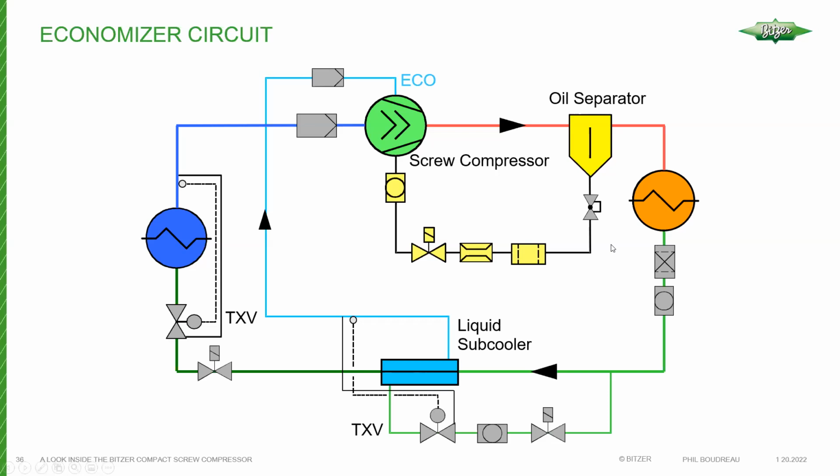So if it's a system that's designed for 105 condensing, if we factor in a little bit of subcooling, maybe you're running 100 condensing, something like that, 95 condensing. But when we enable a subcooling circuit like this, what we've done is added a heat exchanger here. Note that it's piped in counterflow, so the main liquid going to the evaporator travels this way, and the refrigerant that is going to boil on the one side of the heat exchanger, most commonly a braze plate, from what I've seen. Okay, so that refrigerant will evaporate and travel through the heat exchanger in the opposite direction, hence the term counterflow.